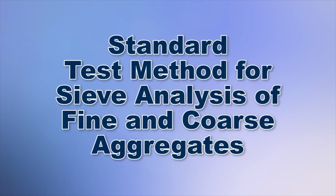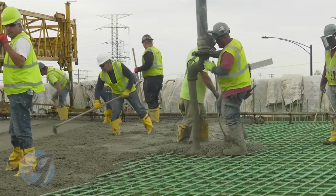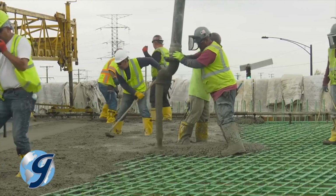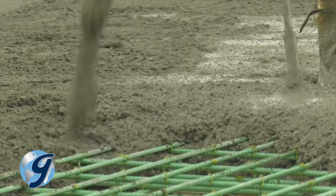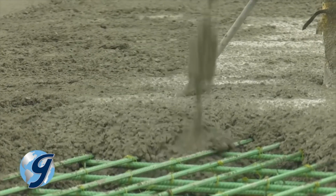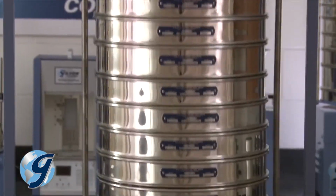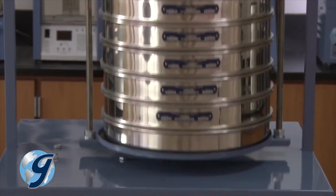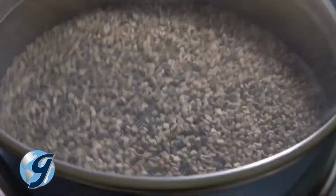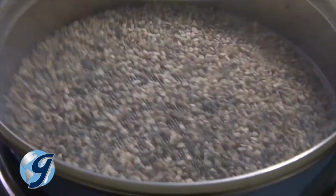Quality control is of utmost importance in construction. During a project, you never want to discover that the aggregate product you're using is ineffective or worse, unsafe. A sieve analysis or gradation test determines the distribution of aggregate particles by size. This information can then be used to determine if the material will comply with design and production requirements.